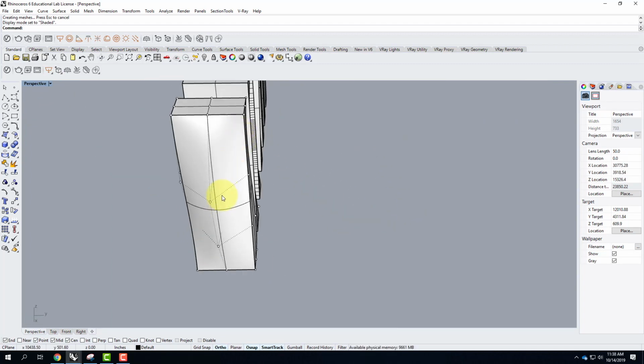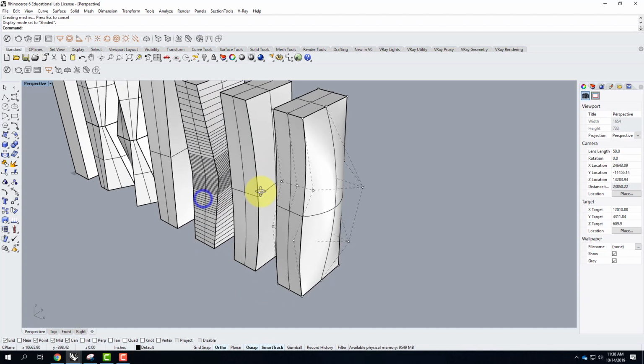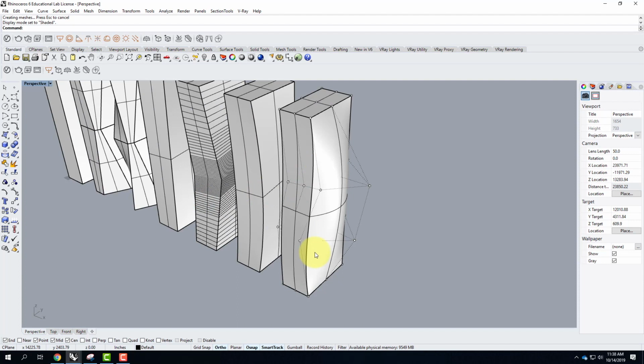This side, however, curves in 2 directions. So it's kind of like a globe. If you were to unroll a globe, or let's do an orange. You can't unpeel an orange without breaking the peel somewhere. You can't just suddenly make it flat. So if we were going to create this as an unrollable surface that we could laser cut, this would never work. Could we 3D print this shape? Absolutely. So you just have to be aware of what kind of methods you could ultimately do.